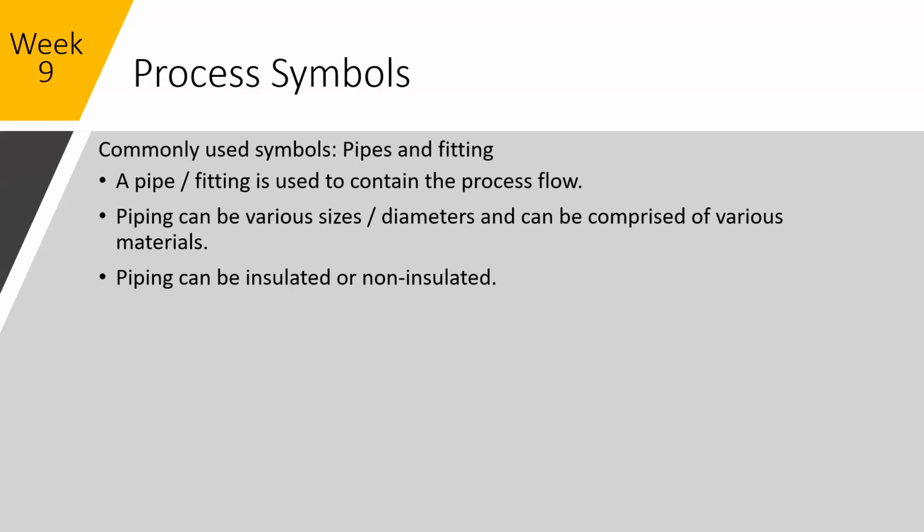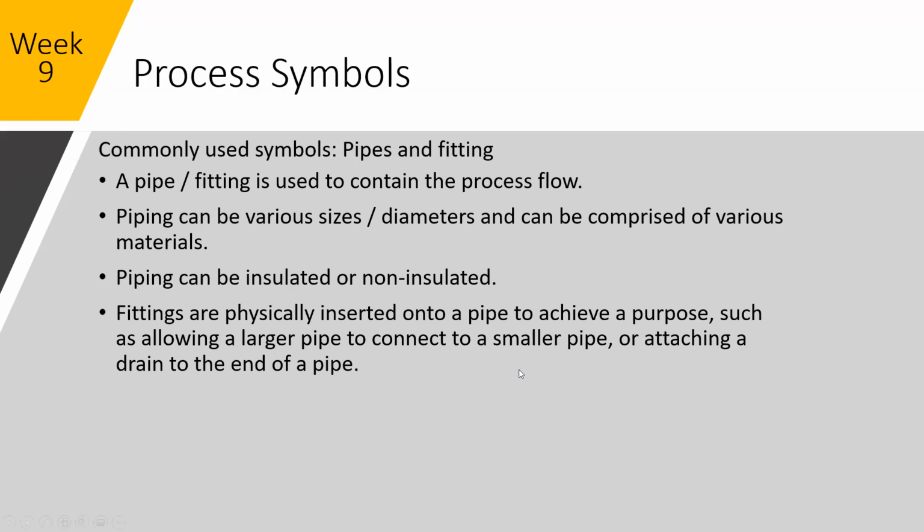That means exactly that. And then you can actively or passively insulate them. And then fittings are physically inserted into the pipe to achieve some purpose. So whether that's restrict flow, connect to a larger or smaller pipe, a drain, a blind flange, which is just dead ending it. Fittings are even mounting pipes, pumps and devices in there. So when you connect a pump to it, you're going to have some kind of flange fitting.